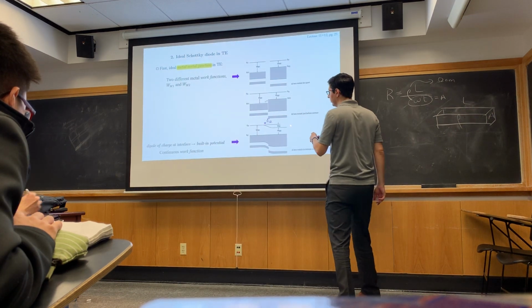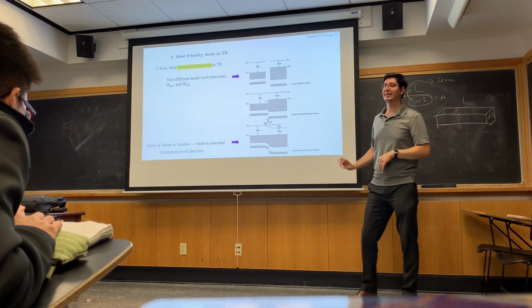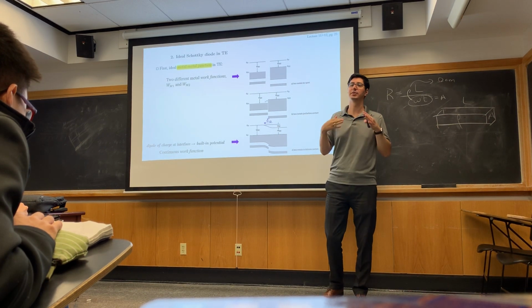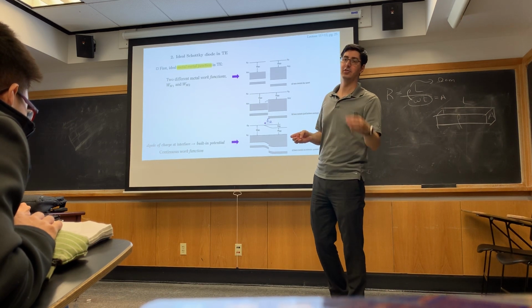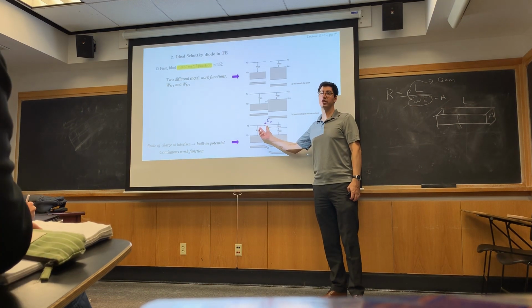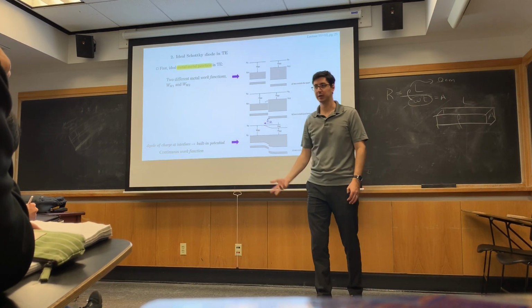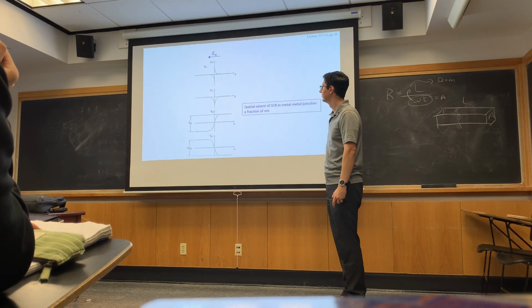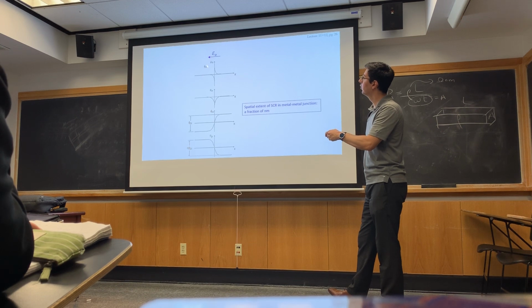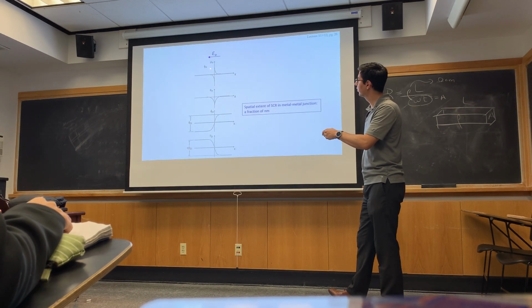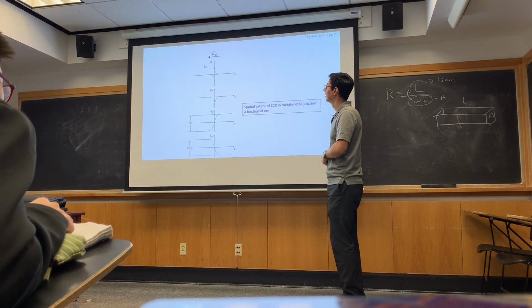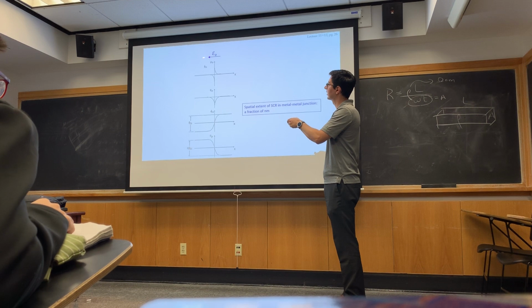Okay, and the reason the local vacuum level is useful is it exactly mirrors the potential. If I look at my local vacuum level, I can see the potential across my device. My potential is just the negative of the change of that. Why? Because the energies for electrons are negative Q phi, where phi is my electrostatic potential. Okay? So for this metal-metal junction, my rho, my net volume charge, would look something like this. That would give me an electric field that way.